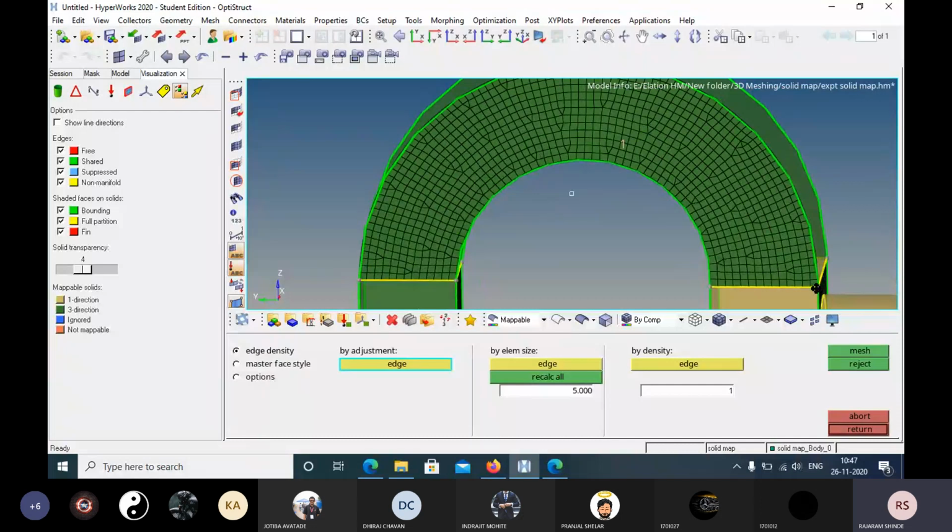That triangles you have to remove. Now on this edge there are 30 elements and 30. Here on this side we cannot modify. Here you can see this in bracket. Why? Because this part is already meshed. This part is already meshed. Okay, I will make it 30 and say mesh.